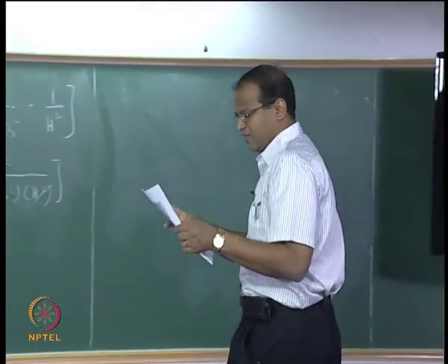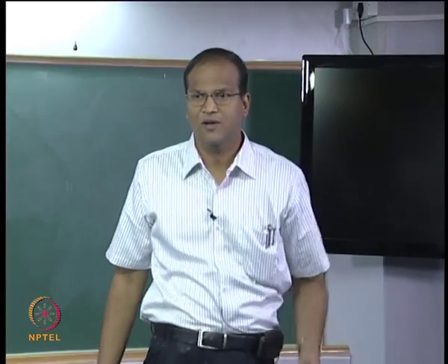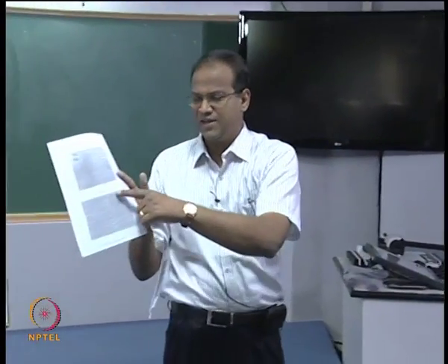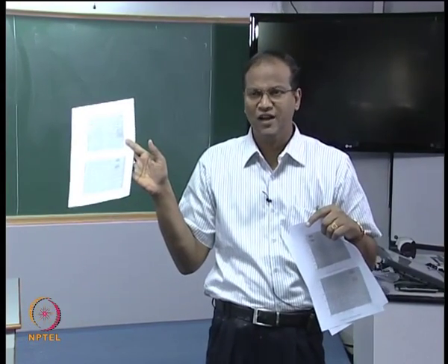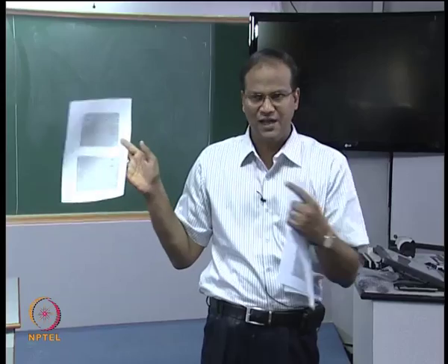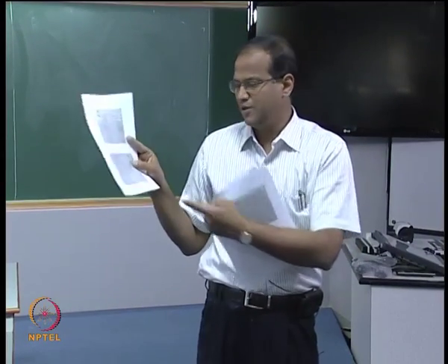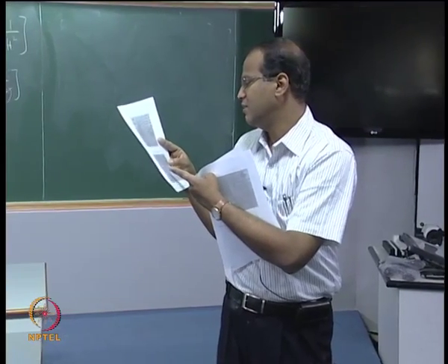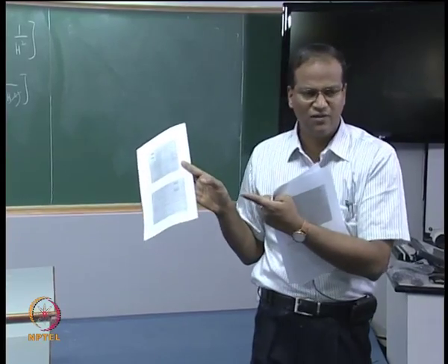As far as the disk is concerned, if your furnace is in the form of a frustum of a cone, you need the view factor from top to bottom, which is for unequal areas. The general formula is for 2 discs of unequal areas, and equal area will be a special case. L by Ri will be on the x axis for the 2 coaxial parallel discs, and the other variable is Rj by L. Please look at it carefully.